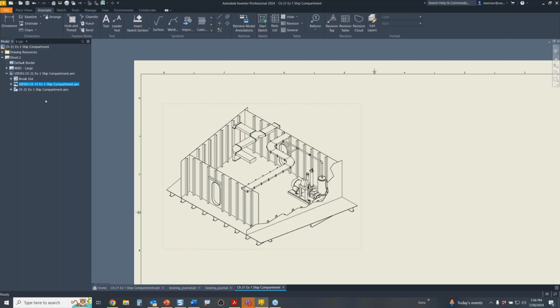So I select the view. First thing you've got to do is expand the view. You can expand the assembly in the browser. So here's the HVAC stuff. Well, you select it, and then if you look, when you select it, your layers are grayed out. You can't do anything. And this is very frustrating. So here is the tip, the secret. You right-click on this assembly and use this option, Select as Edges.